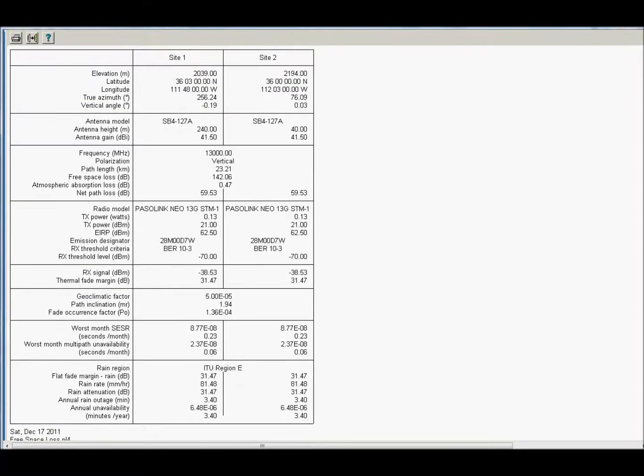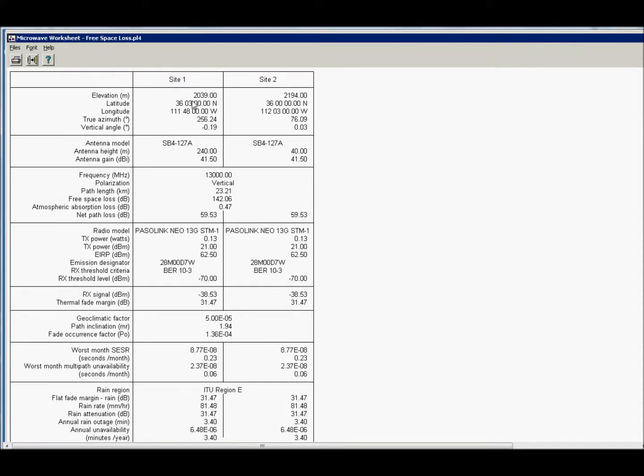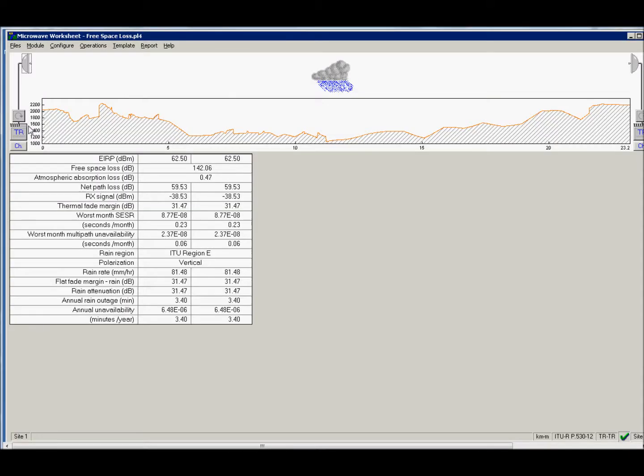I'll keep it this way, and I'll choose this lower frequency because in future I want to get high capacities without changing frequency range. That means without losing extra money changing antennas. If I'm happy with 32 megabits, I stick to 18G because it's cheaper.